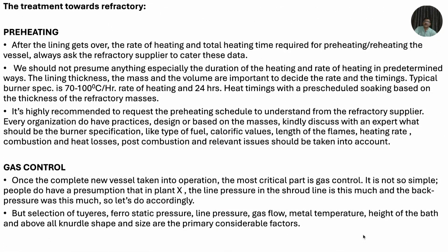The treatment towards refractory: the very first point is preheating. After the lining gets over, the rate of heating and total heating time required for preheating, reheating the vessel. Always ask the refractory supplier to cater these data. We should not presume anything, especially the duration and rate of heating, in predetermined ways. The lining thickness, the mass, and the volume are important to decide the rate and the timings.